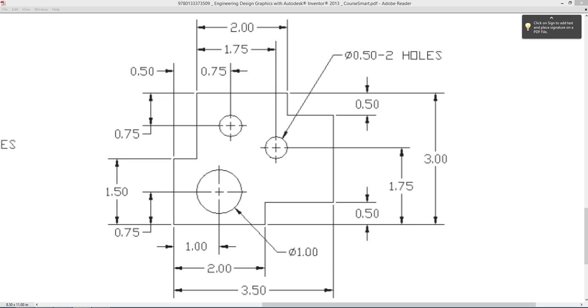Exercise P1-4 is a pretty complicated item. It's a weird shaped block with three different holes in the center of it. The three holes are two different sizes. So for this one, we're just going to draw the outside shape, extrude it by its thickness, which is 1.125, and then we're going to go back and add the holes. And again, this one here is in inches.